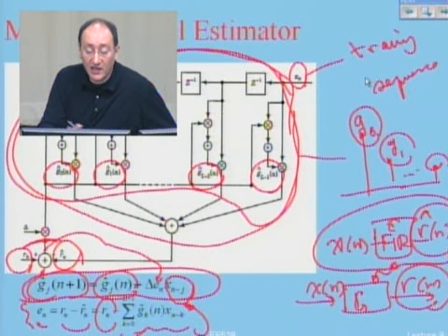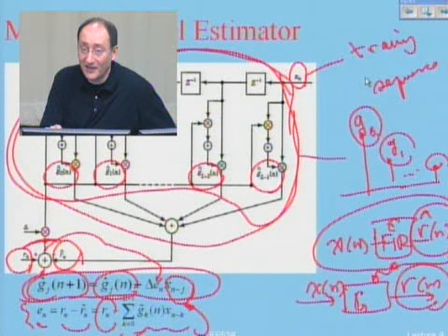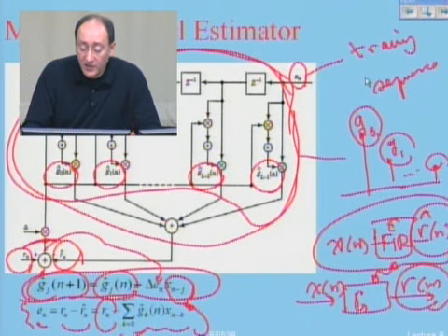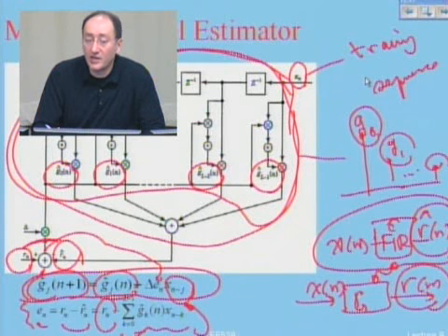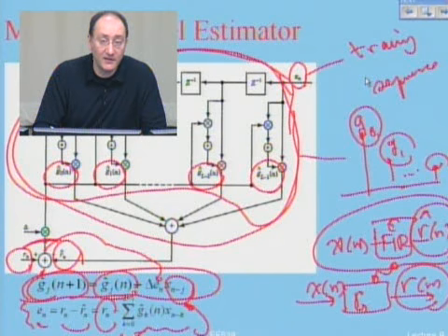For the details of implementation and the proof, the best reference could be John Proakis's book. For older material, my thesis from 1979 has this stuff. But the point up to here is that you have simple structures available in the literature with which you can estimate the channel impulse response.